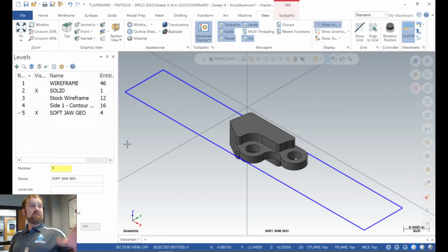Now, if I've got a wider part that I'm holding on to, like this indicator here, that's how we do side 2 of this. We cut a jaw this shape and we hold it. If I'm holding on to this, I might have an inch gap between the jaws. I'll put a parallel in there down in the bed of the vise, close it on the parallel to hold it tight, and then cut the pocket for the shape of the part. It's a little part. Okay, minimal.